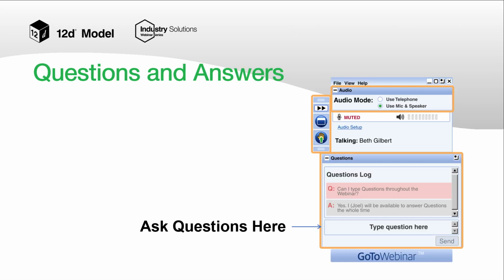Okay, so we had a question through from Simon saying, if you modify the catchment boundaries, are those modifications considered and/or remembered if you run it again? Yep. So I assume that the purpose of that question was for if you try to run it again with the process network option. If you have clean model beforehand ticked, it will erase all of the catchments that you've previously drawn. So if you have modifications that you want to keep, I would highly recommend unticking that option first. So I suppose short answer, no.